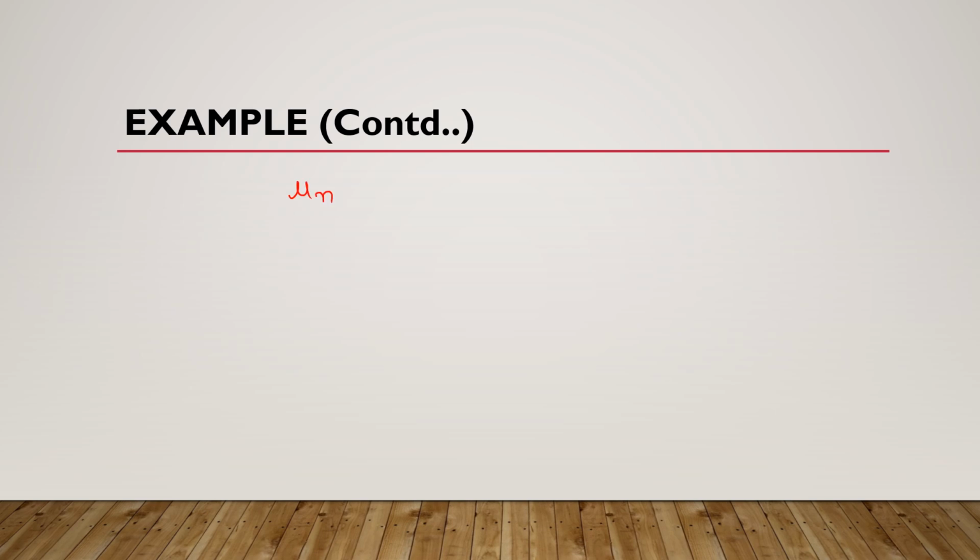Okay. Now here mobility of free electrons is 450 centimeters square per volt second. As you can see here, this term is in centimeter. Now we want to convert it into meter. So we get 0.045 meter square per volt second. Okay. Now we have the values of mobility of electrons as well as capacitance of oxide layer.